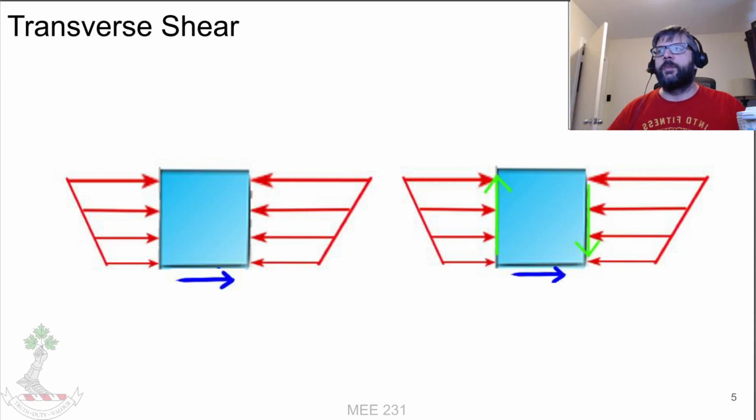The forces will be in equilibrium, but it will still have a tendency to rotate. So we need to add a moment couple on these faces in order to prevent them from rotating. This is what we talked about when we looked at the forces on the cube that define how shear acts.